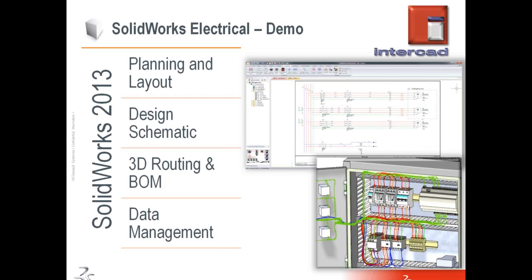Third, 3D routing and bill of material. Here we will look into the 3D side, how the wiring and the cables get routed, and how it calculates the accurate length of the wire or the cable, whatever you route, and includes those lengths in the bill of material that we will create at the end.